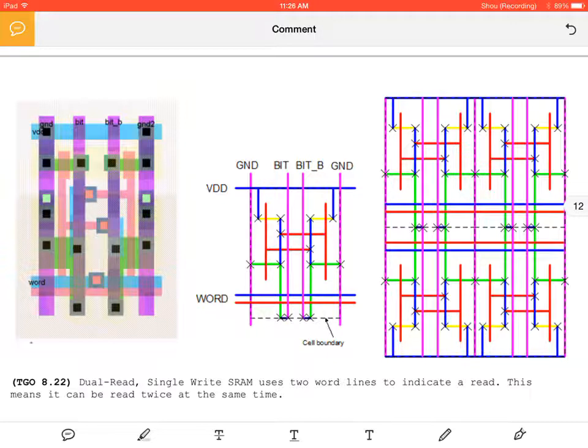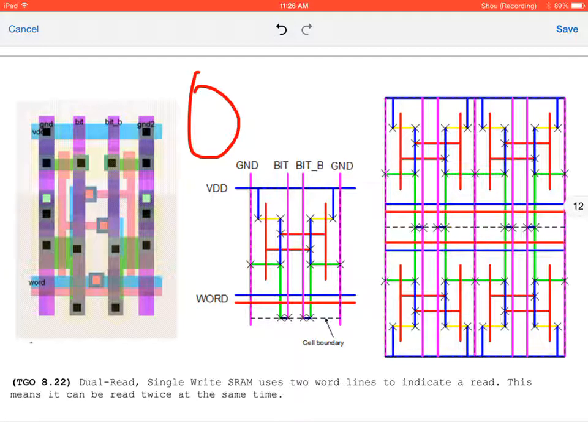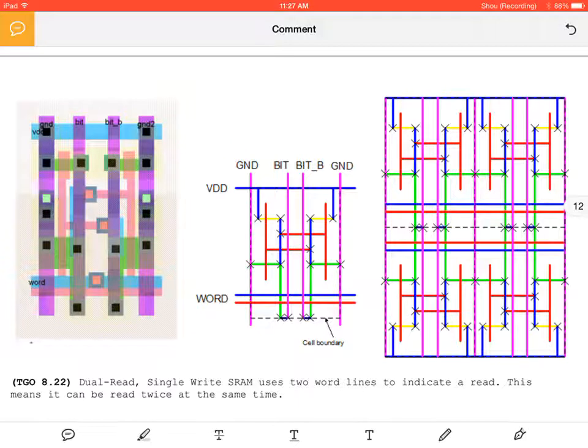If you remember back in section 5 when we talked about wires, I presented a problem where I believe it was 85% of the wires go to memory and then 15% are in processing. And we were calculating the power consumption based on the switching factor. So these have lower switching factor, like 0.06, whereas the switching factor on average was 0.5 for processing elements. And we also know that the power consumption of wires is directly related to the length, right? So by using layout overlap, especially in memory elements, you can significantly reduce the power consumption of the chip because you're reducing the length of the wires and you're still getting the same results. I hope that's a good combining concepts concept.